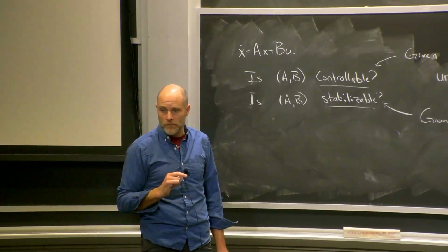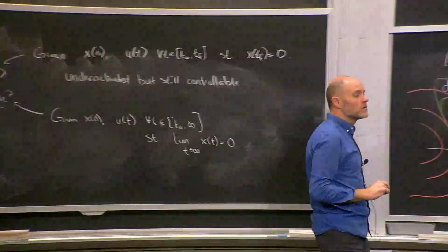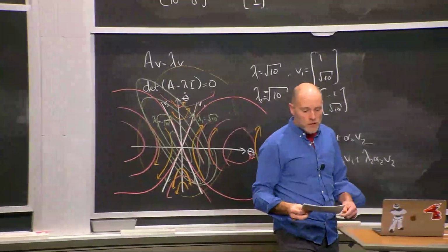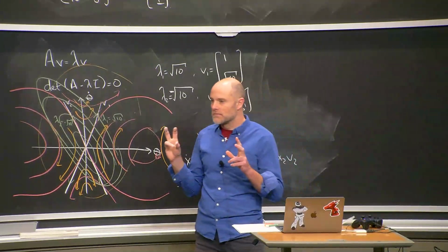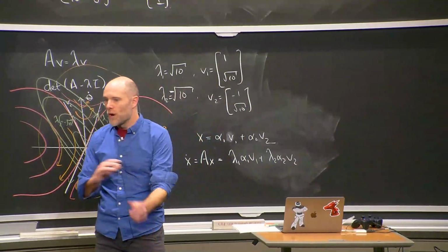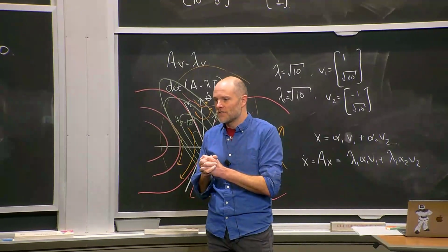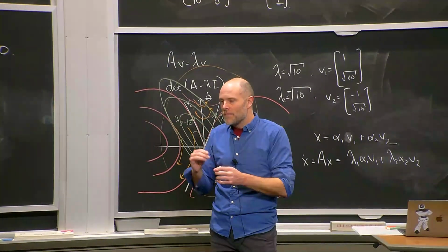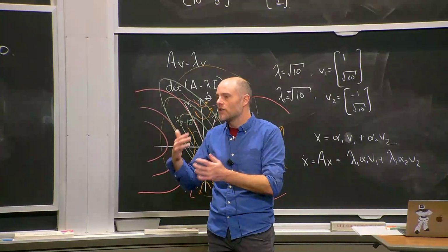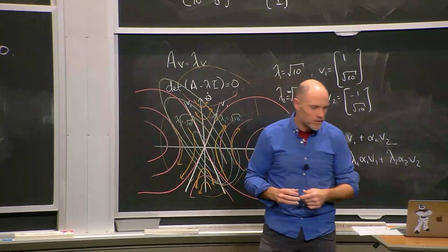So maybe practically this finite time will be so long that it becomes irrelevant. That's true. Oftentimes people talk about controllability as a Boolean thing, but really the rank of the controllability matrix is binary, or it's an integer, but the condition number of that would tell you how controllable you are, and that's probably more relevant in practice. I completely agree with that.